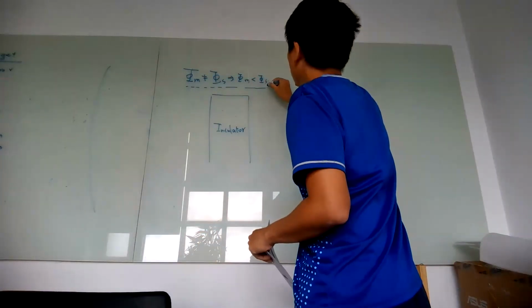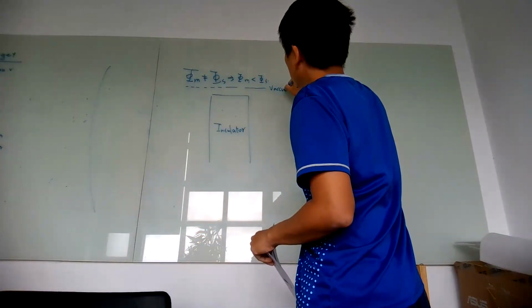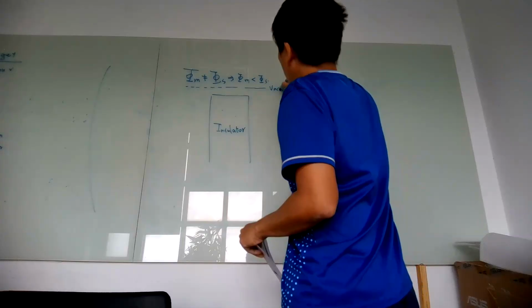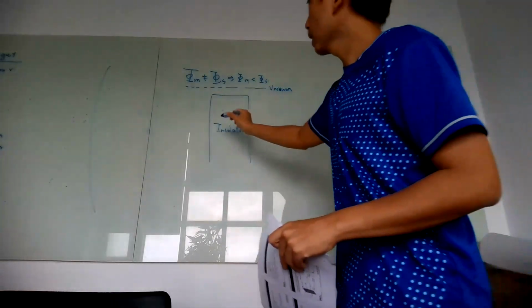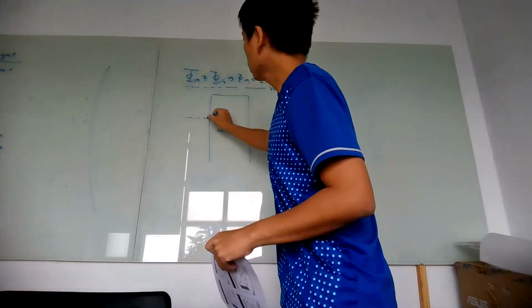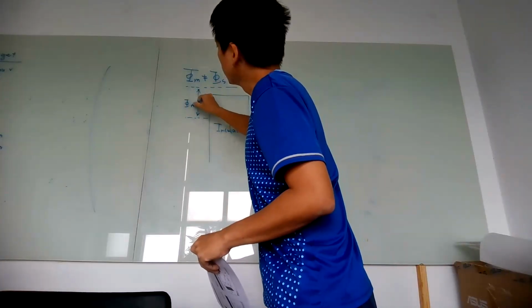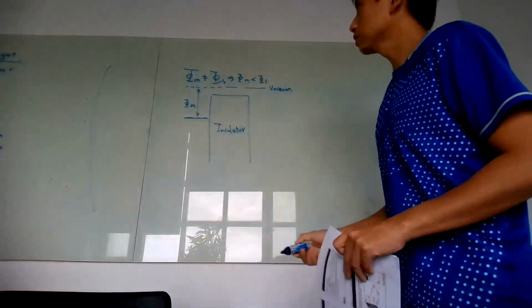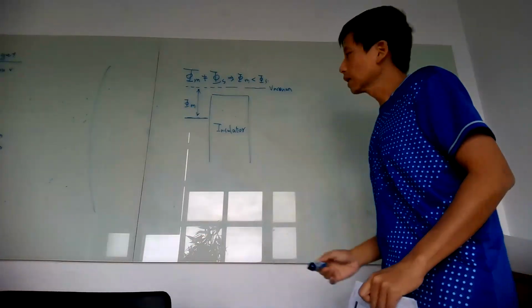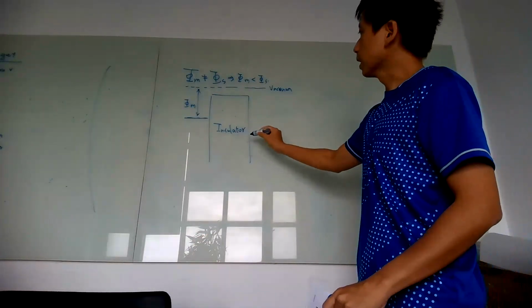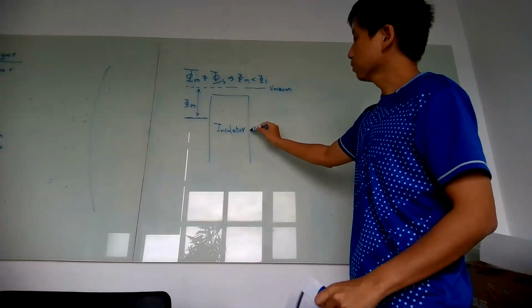What does this mean? If you have a vacuum level on top of this layer, so here's the vacuum, ideally we get the work function defined in the metal, which is here. So it is phi_m. You can consider the electron Fermi level is here.